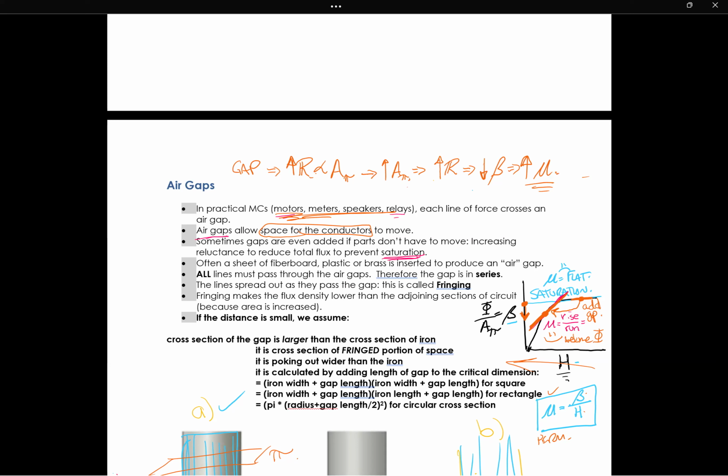So it's very important that we know the relationship is that with an increase in surface area, we increase the reluctance, therefore we decrease the flux density, and decreasing the flux density brings you down on this BH curve, which brings you to a slope, rise over run, that is going to be greater than it was before, which makes you more welcoming to flux being established, which is a beautiful thing. So what I was describing here is how this part works.